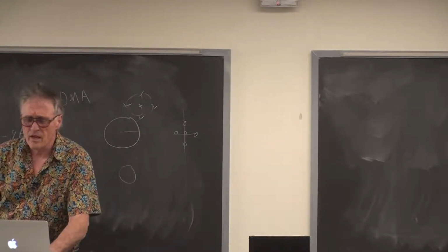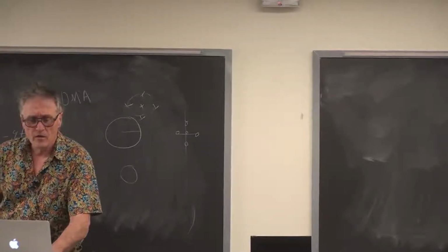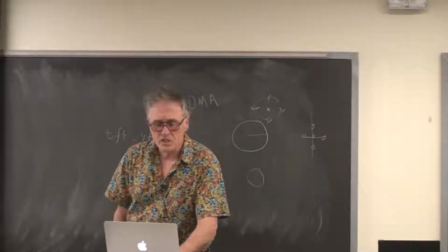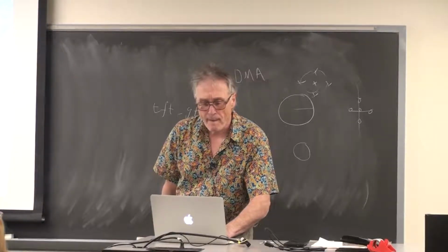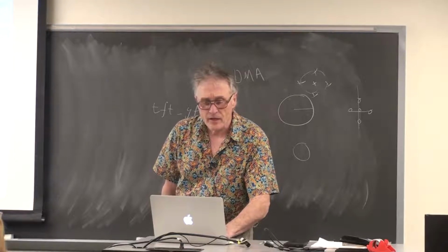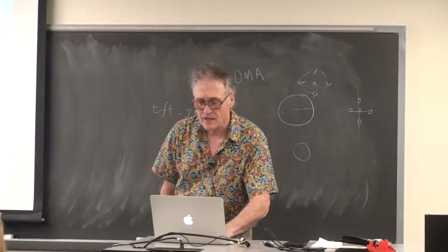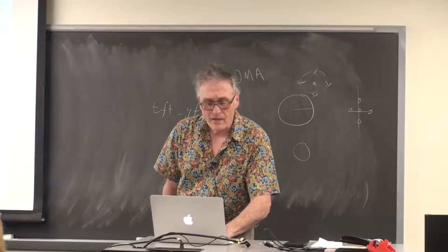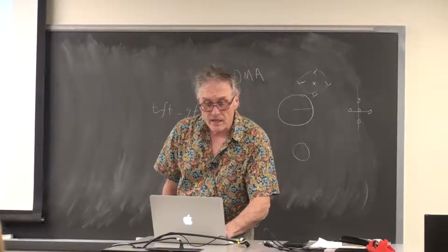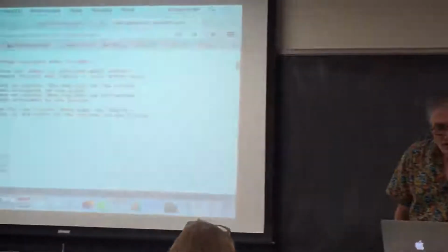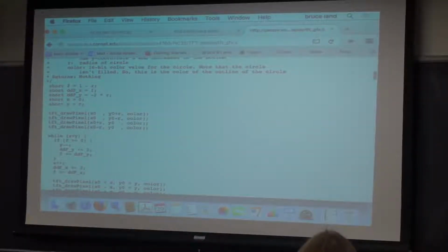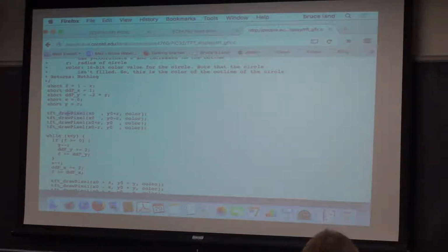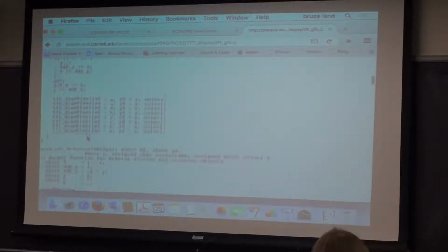If you go into the, can I get to the GFX stuff here? I don't think I exposed, yes, there it is, tftgfx.c. So if we go plowing down through here, oh, the very first thing is TFT draw circle. And so you look at this, and there's a whole bunch of arithmetic that goes on, and then TFT draw pixel with plus and minus the radius and a color. You could just call TFT draw pixel directly yourself. Save all of this overhead of doing all these calculations.